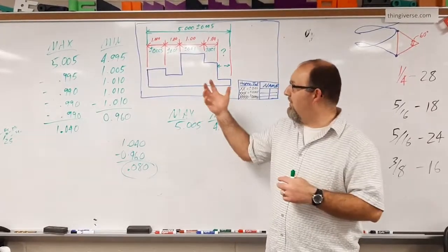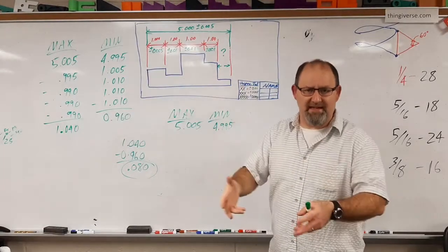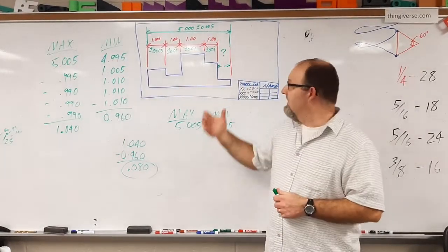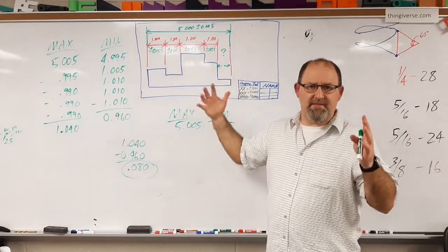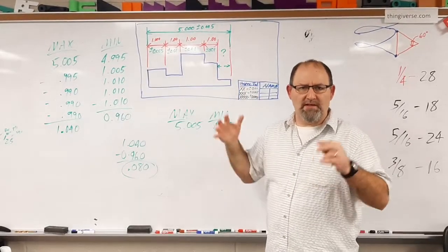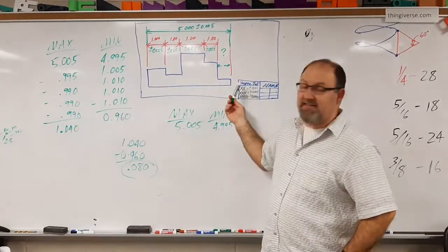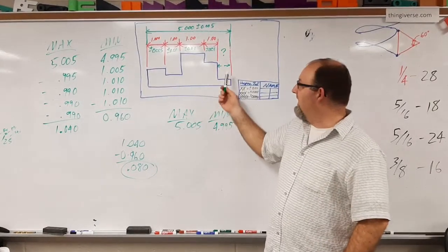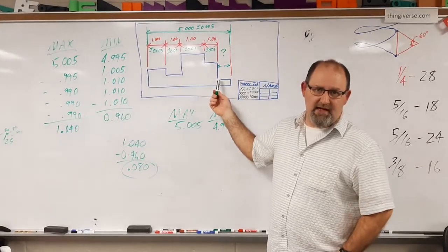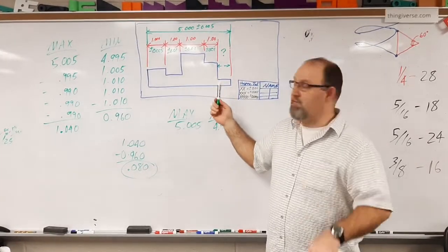But if you have parts that are mating, so if this plate was laying into, let's say, another part, sometimes engineers and designers will want limit controls on those parts or the outside controls. And so it just has a tighter overall control, but the tolerance is still here in the runout area.